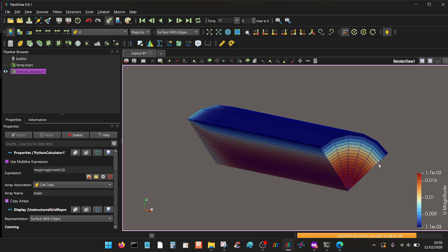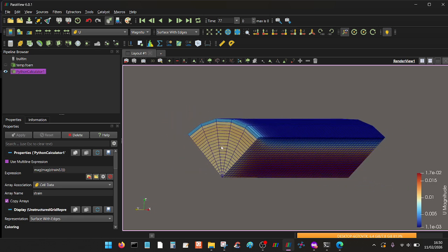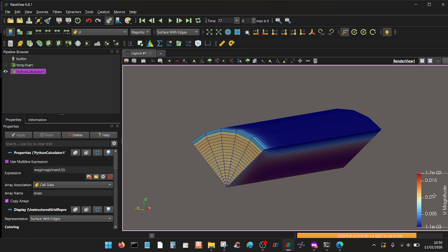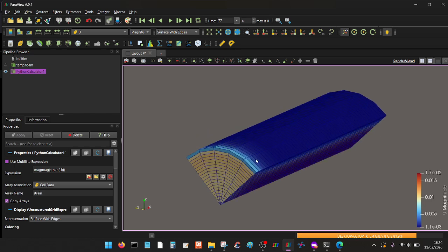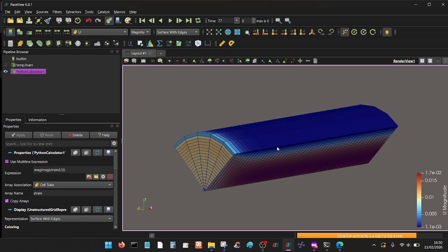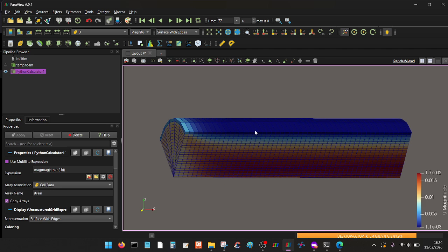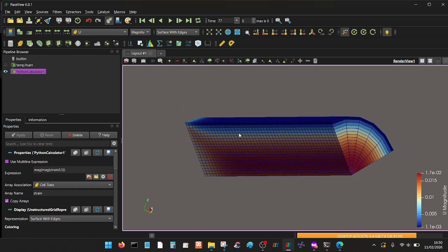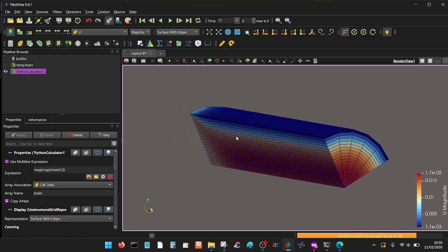I think in this case I specified an inlet velocity of 0.01 meters a second. It could be quite different to that, but I've just guessed it. The dimensions of this I've estimated as a diameter of 1 millimeter. So the length of this is only 2 millimeters. I've just done a really small section of pipe as if it was some sort of needle.